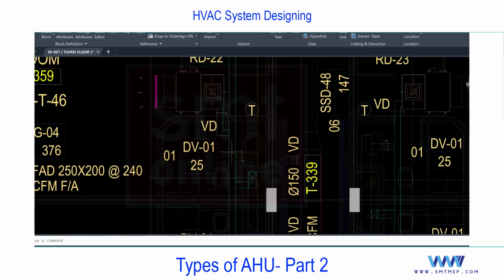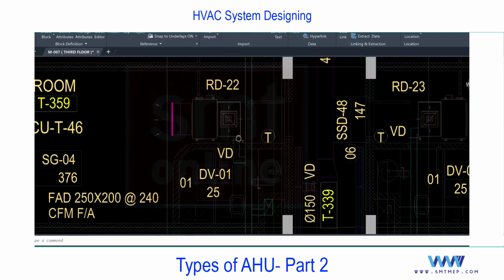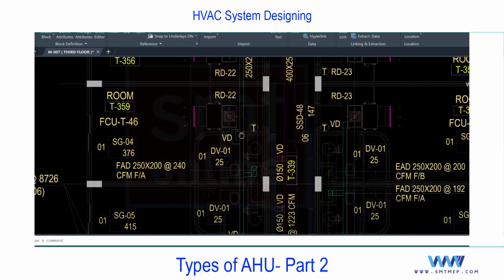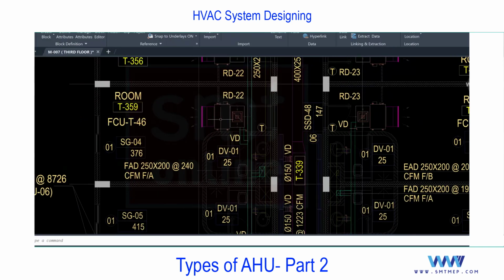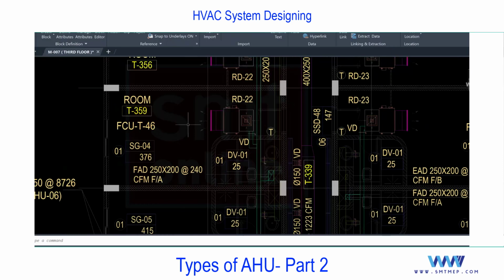Supplying the fresh air from the blower, sorry, from the exhaust, from the normal fan, not FAHU, to this box. In this case, the heat of the fresh air is going to be borne by this unit. If you're using a separate FAHU, in the load calculation we are not considering the heat of the fresh air, but at the time of considering this unit. This is also an important point. We'll discuss at the time of load calculation.